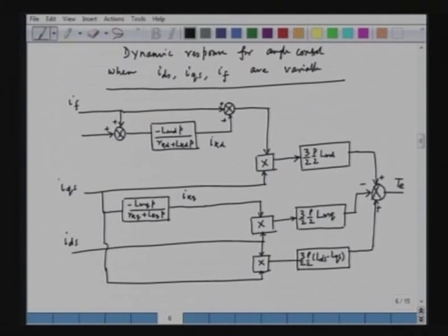Now, we have already seen how complicated the equation for the torque is. Here this is a general situation where everything is variable, gamma is not equal to 0, which is angle control, and all possible torque is present here, the field torque, the damper winding torque and the reluctance torque. So, this is a very general situation. Now, as I was saying a little earlier, we have vector control, which means gamma equal to 0, the torque response is very good, and when gamma is not equal to 0, we call it angle control.